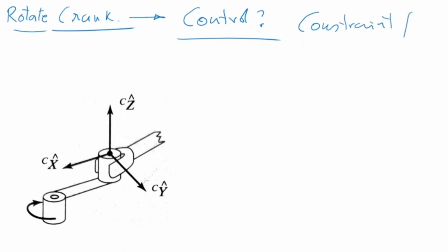Okay. So a constraint frame is first fixed here. Now this frame, XC, YC and ZC, is the frame which is fitted onto that. So my force and positions are going to be applied with respect to this frame now. Okay. Now if you look at this frame, we can divide the forces and motions into natural constraints and artificial constraints.